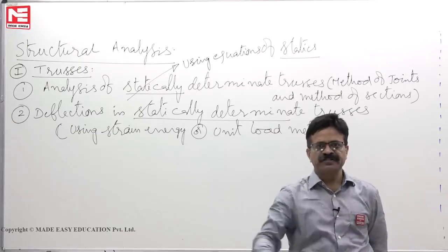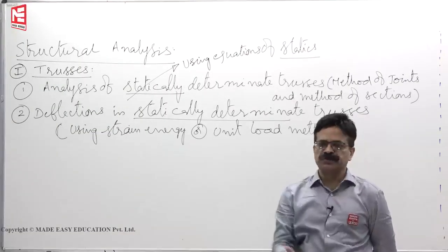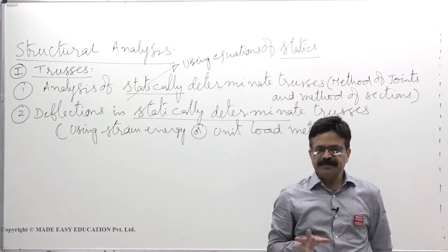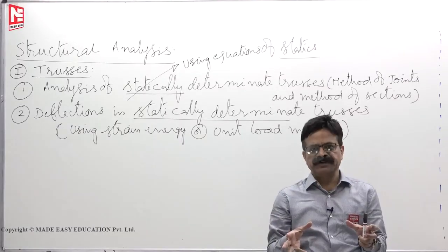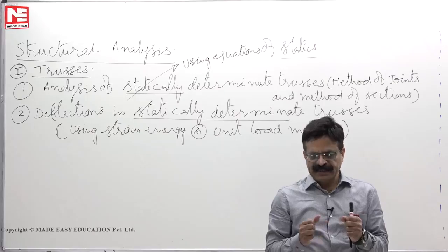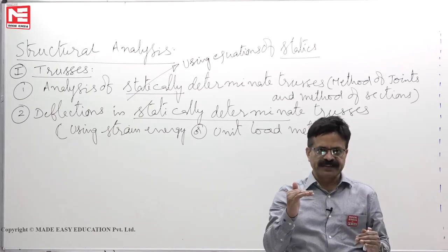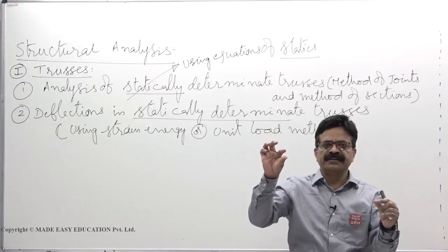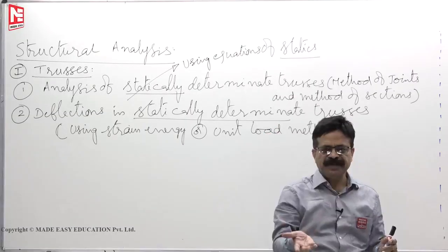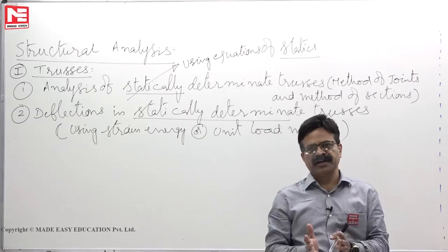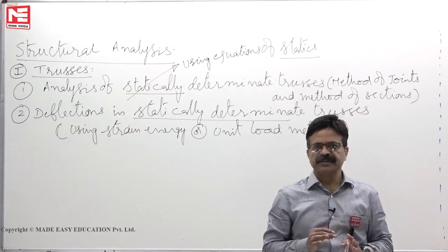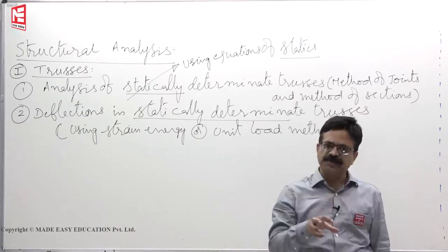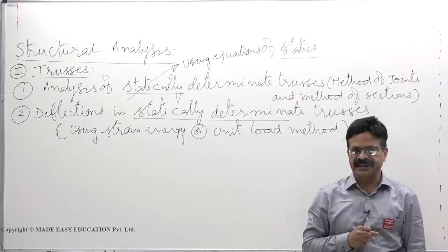When you are moving on the structure, if it deflects too much, you won't be comfortable. Sometimes any machinery equipment you are keeping, if it deflects too much, then the shafts or beams bend, and the purpose for which you built those machine components will not be served. That is why the stiffness criteria is equally important.